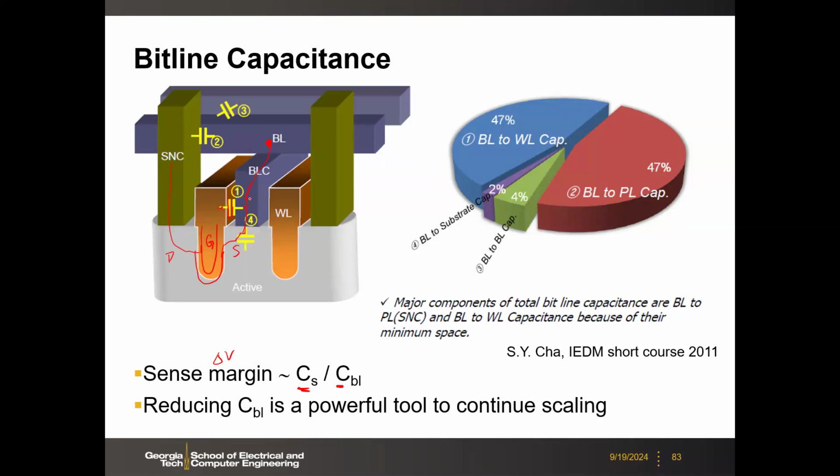And then your Bitline itself will pass, let's say, adjacent to the standing capacitor, right? The cylinder. So your Bitline will be adjacent to that. Then you will have this coupling from the Bitline to the storage capacitor. And then, of course, between Bitlines, from wire to wire, you have the isolation, then you have the capacitance. So all those capacitances will add up together as your CBL, right?